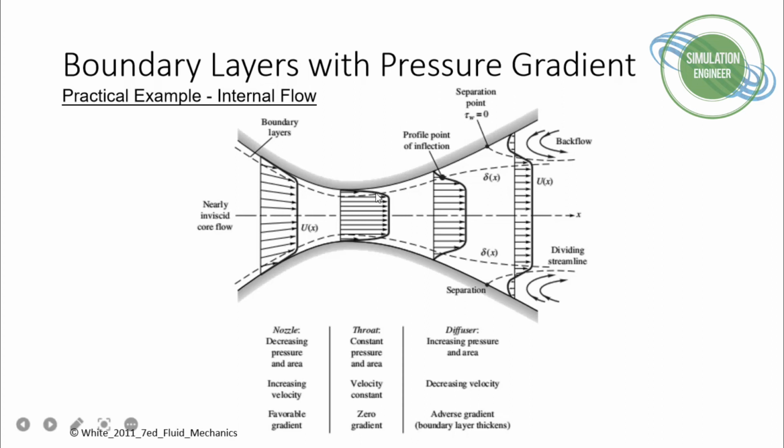And then the flow tries to follow the geometry, because now you will be getting this diffused effect. So it's kind of a diffuser effect. If you go further downstream, it's the same principle as we have seen before in the flat plate, a general case: initially it will be a weakly adverse pressure gradient, then it would start to become a little bit intermediate, and at this point you will see that now the pressure starts to dominate the flow, and the velocity is becoming a little bit less, because we can see from the velocity vectors, the magnitude of velocity is really quite strong here, and all of a sudden once you move here, you will see this change in the curvature.